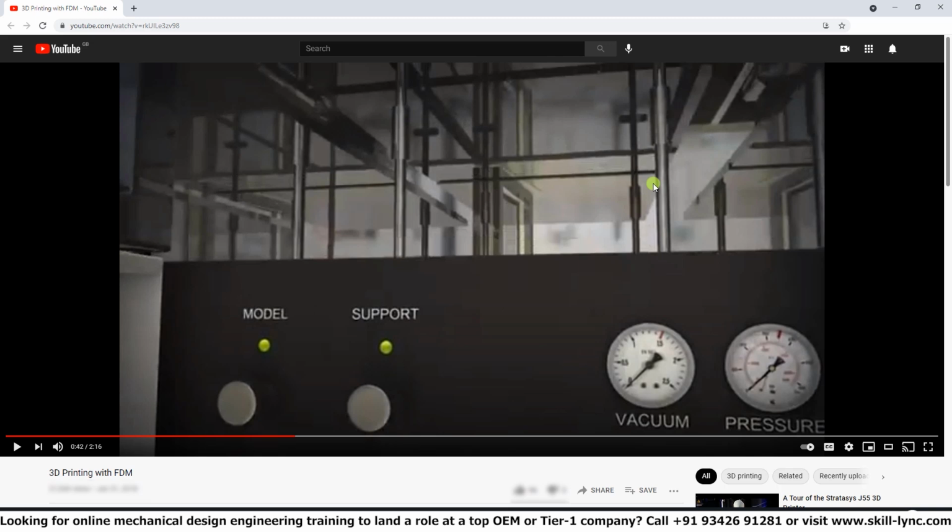Let's say if you have one of these 3D printers, not this one in the example, but a different commercially available one that doesn't have an enclosed box, and you put it inside your office or room, and you have a window open and there's a draft of air, that could also affect the quality of the models that it produces.